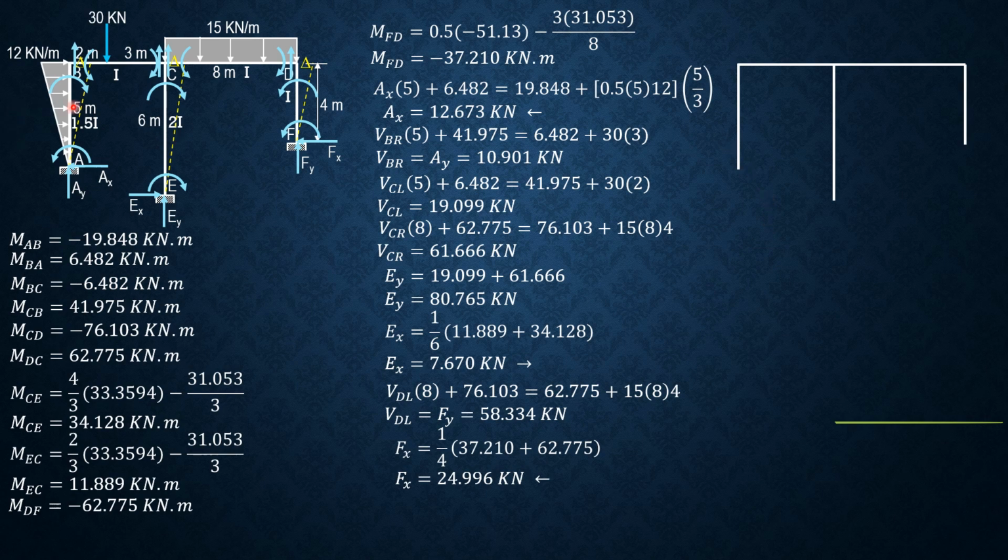So top fiber here, top, right, and right for this column. So for first AX, so positive AX, which is 12.673 to the left, because this is the top fiber here, 12.673, then minus 1/2 of 5 times 12, negative increasing. So we have negative 17.327. So let's have this distance later.